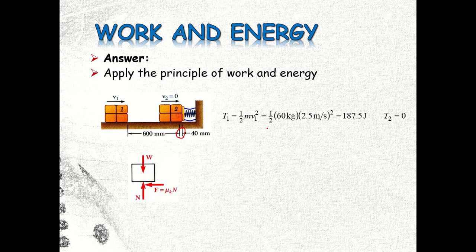Alright, now resolving this illustration here into these forces. So we have the weight of the package, and there's a force normal to that on the surface, and we have the friction that will oppose the movement of the package to the right. So of course it should be going to the left. So we have this relation that this force F here going to the left, that is the frictional force, will be the product of the coefficient of friction and normal force.